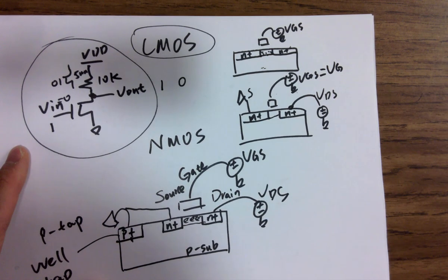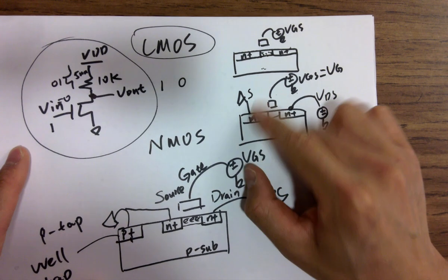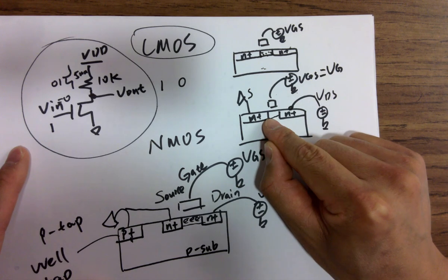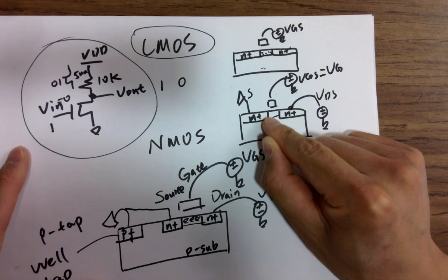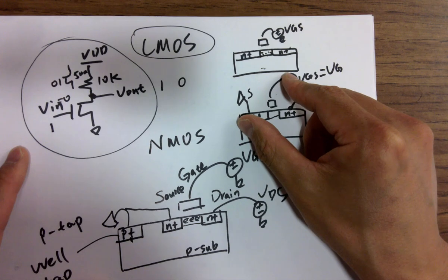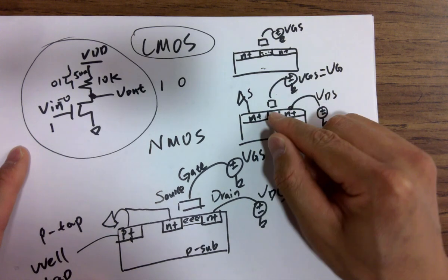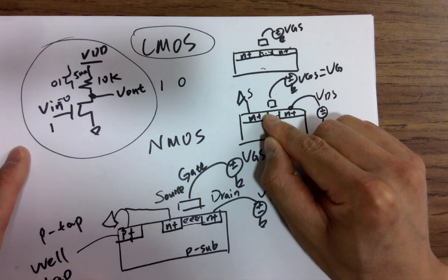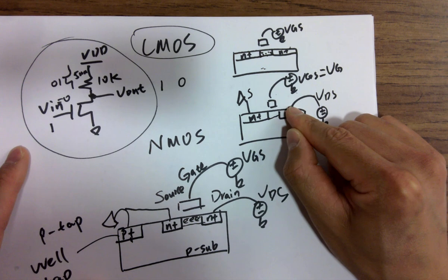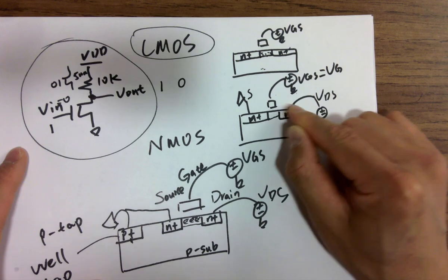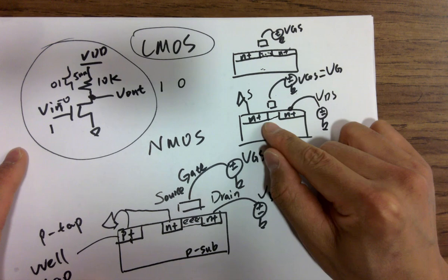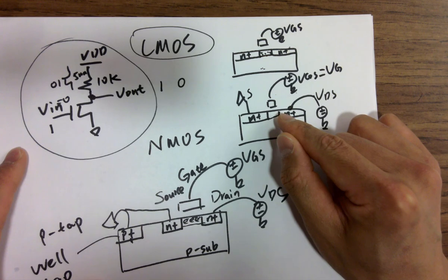The voltage difference between G and S is pretty big, so you can imagine a stronger electric field, and it's getting a thicker electron channel over here. For the drain terminal, because you have a higher voltage here, it's reducing the depth of the electron channel, so it moves up a little bit.